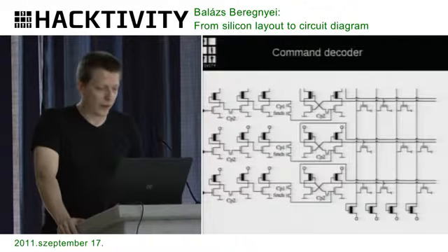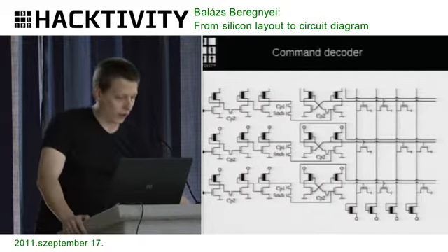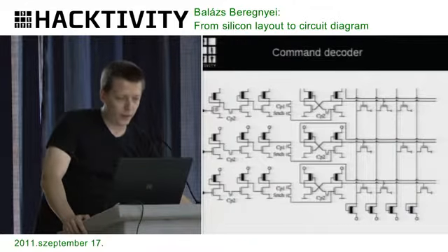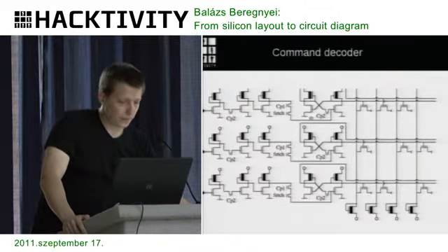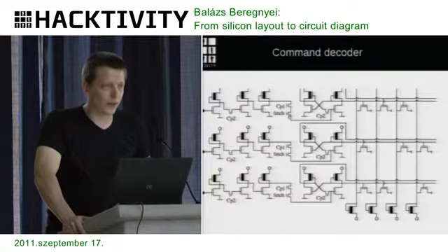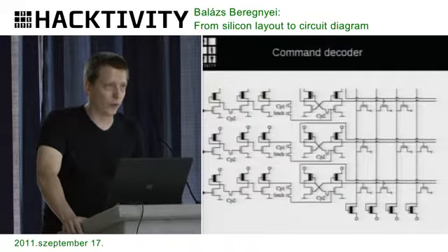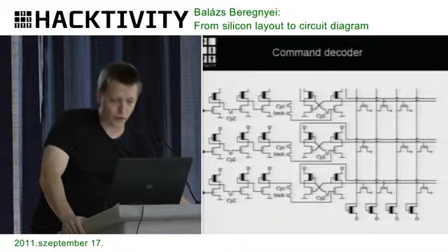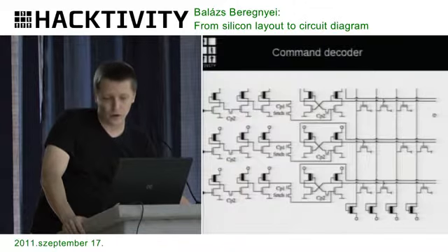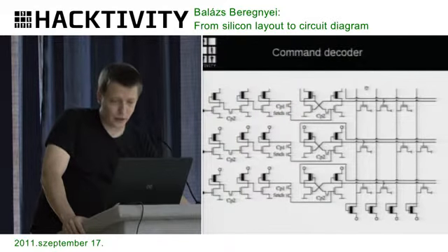This is a section of the command decoder. You can see the operating code comes in, a couple of inverters, transfer gates, and goes into the command register. 1 bit storage here. We needed transfer bits because we don't have to input each and every bit, because we also have operands that are not allowed to go into it. And here in one cell, either you have a transistor or not.